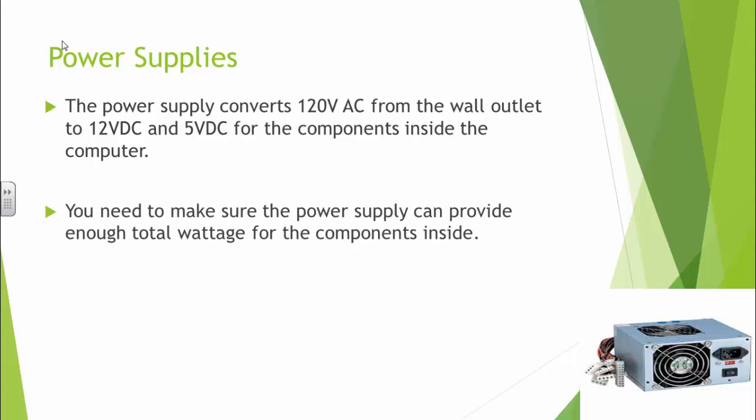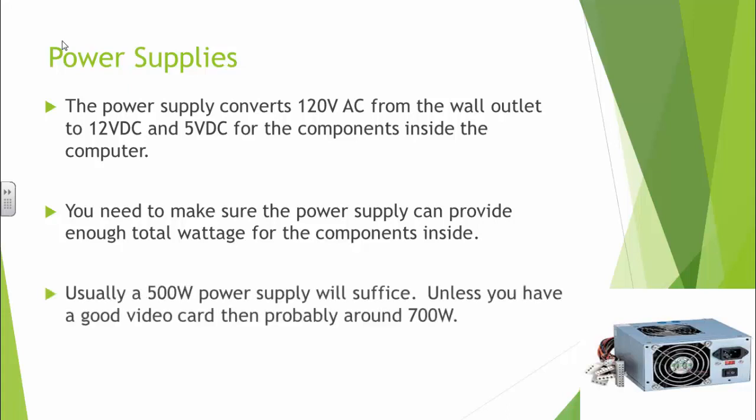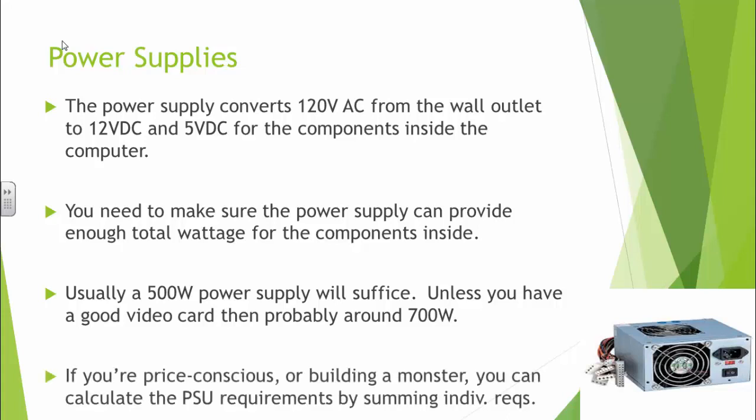Now, the PSU is important. We need to make sure it can provide enough total power for all the components that are inside the computer. Having said that, usually a 500 watt will work. If you have a really good video card, then you might need as much as a 700 watt power supply. In general, you can pretty much use a generic PSU, but if you're being price conscious or if you're building some kind of serious beast, you can actually sum up the individual requirements for each component in your computer and specify your PSU with great accuracy.